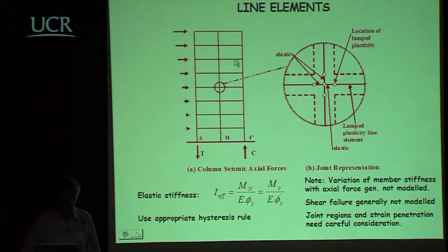Most time history analyses won't take that into account. They will assume that the elastic stiffness remains constant. Now, if we're going well into the inelastic range, that doesn't matter too much because it won't affect the overall structural response. The same thing happens in terms of the strength.